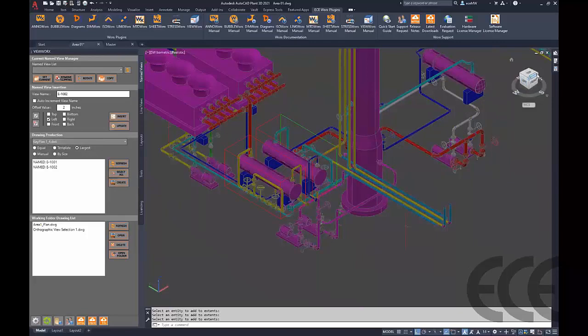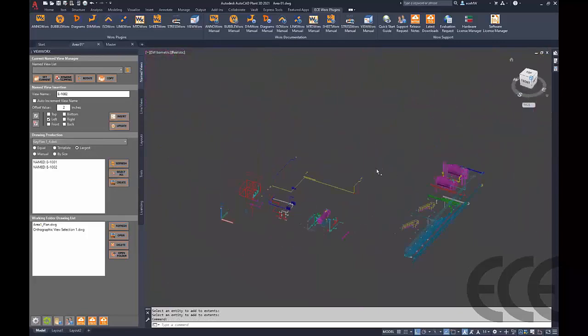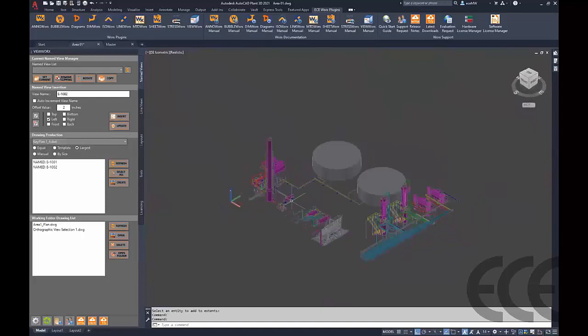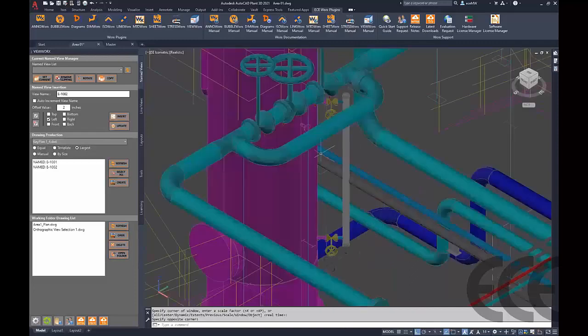If something ever changes in your plan that the whole entire project needs to be rotated, or if you're working with, in this case here, we're going to take a look at one of the level bridles on this tower over on this side. With the level bridle being rotated, when we put our view in, it's not going to really line up. So if you're accustomed to cutting typical views, you've got to get in there and do a DVIEW twist and all that stuff. With ViewWorx, we make it super simple. So we, again, just start off with the name of it.